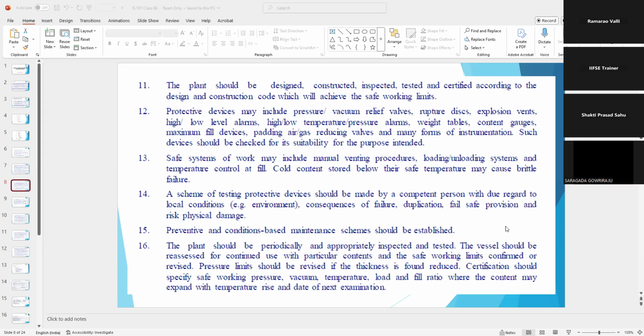In case of high flow, or as well as any other materials coming in, what will be the effect of that change, and what are the various chances of such causes or incidents happening? All this we assess in the hazard operability study.